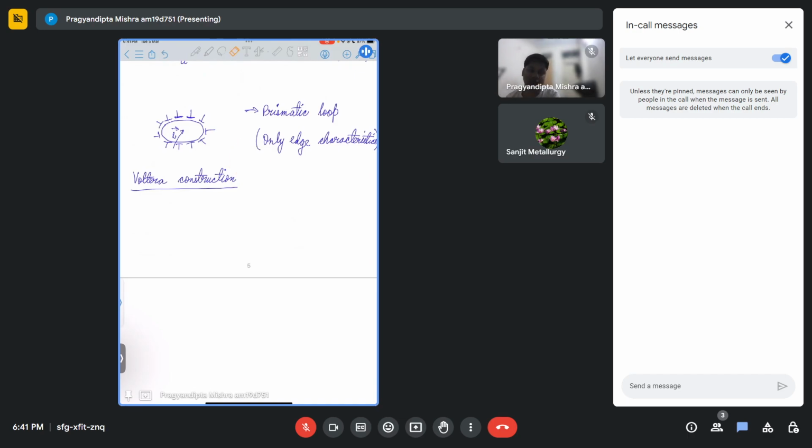Now this construction is used to draw things like dislocations, disinclinations, etc. Now we'll not talk about disinclination. Essentially, disinclinations are like angular openings. It is not like dislocation where you have a one-dimensional defect being present. Disinclinations are used for different purposes. This is not a defect kind of thing that we're looking at. So what we're concerned with is only dislocation. So how do we construct a dislocation with this Volterra construction?